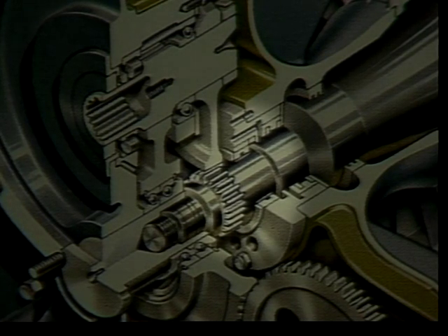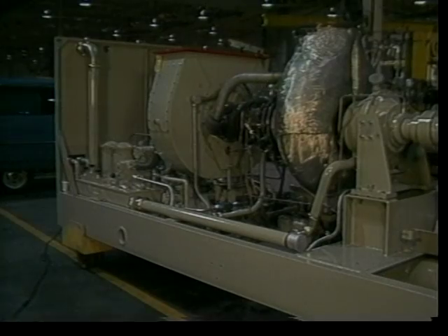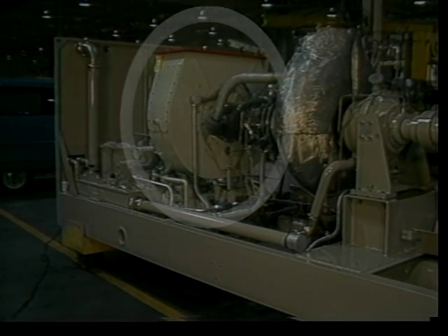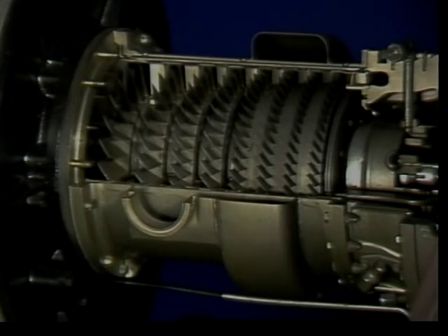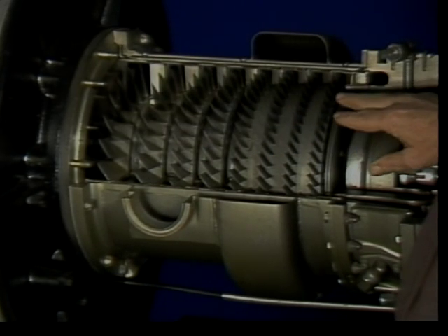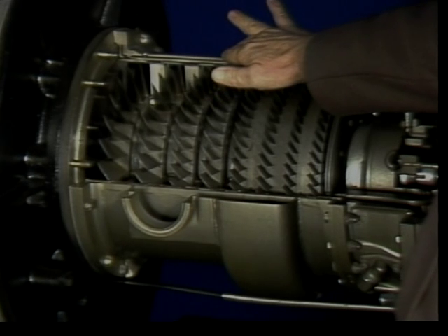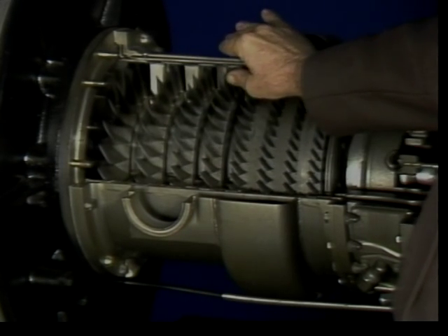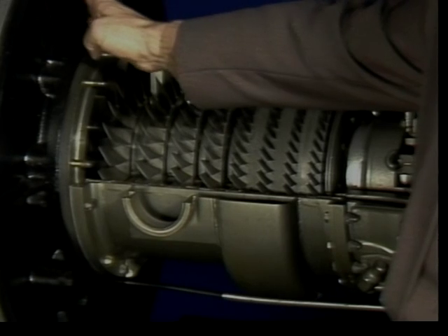Just aft of the accessory drive, the screened air inlet assembly directs air through a 360-degree path into the compressor. The center of the air inlet housing contains the forward compressor rotor bearing which supports the compressor shaft. An air inlet duct fits over the air inlet assembly and directs air into the assembly. The next assembly in line is the compressor. The compressor is an 8-stage axial flow type incorporating a case and balanced rotor assembly. The case is attached to the air inlet housing.